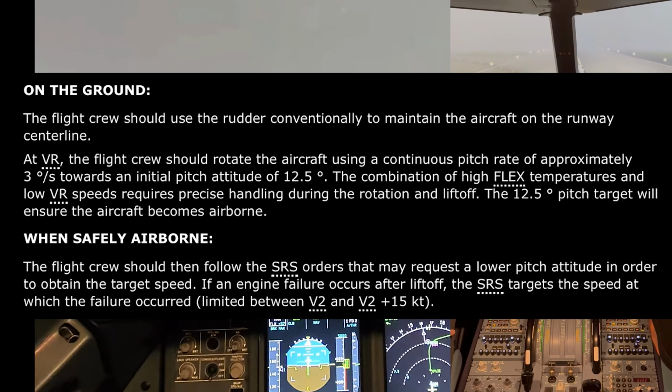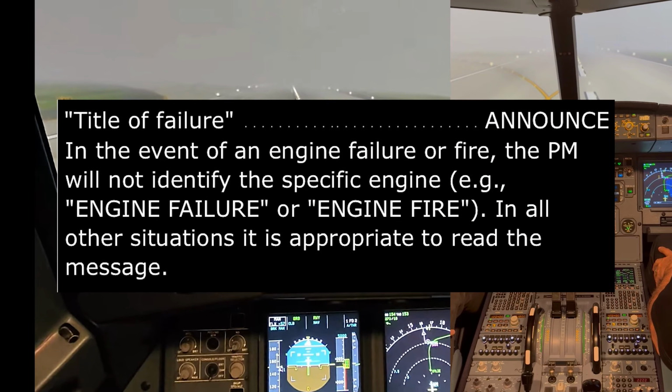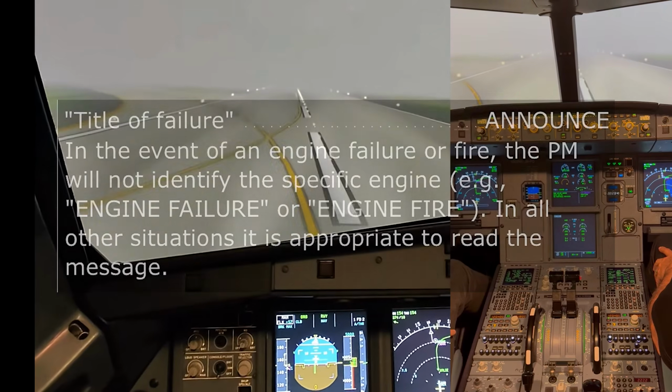At VR, pilot flying rotates by using a continuous pitch rate of approximately 3 degrees per second towards an initial pitch attitude of 12.5 degrees. This will ensure the aircraft becomes airborne. Next, the pilot follows SRS to maintain the appropriate target speed. Notice in addition that pilot monitoring did not identify the specific engine that failed. This is done later on in the procedure. Just announce engine failure.